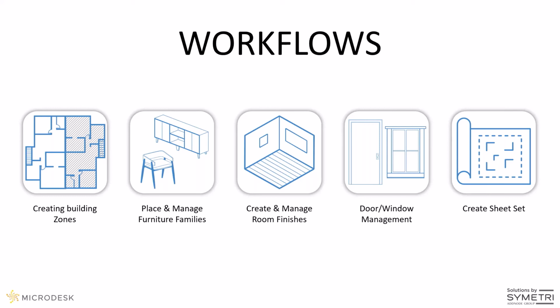We looked at placing and managing our furniture families, being able to easily work with our general company standard content, easily placing them so that we can change up our designs faster and quicker using Naviate's family browser. And then of course, editing or pushing data to our families, automatically updating it and visualizing it.